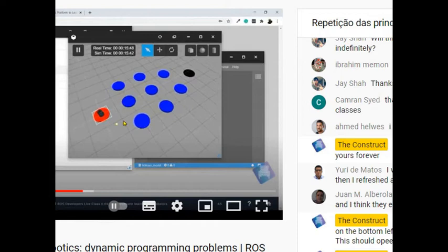The first layer produces this trajectory in purple, and later the second layer makes the trajectory smoother in speed and path profile. And then we have this pink trajectory here, avoiding the obstacle that's on the left of the car.